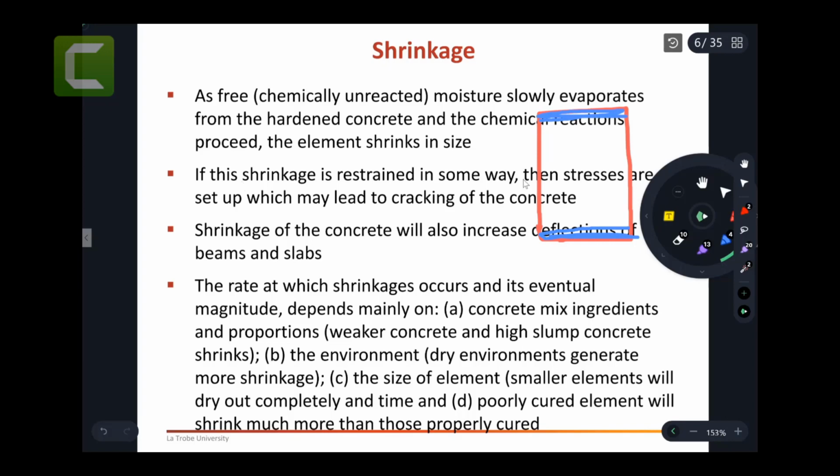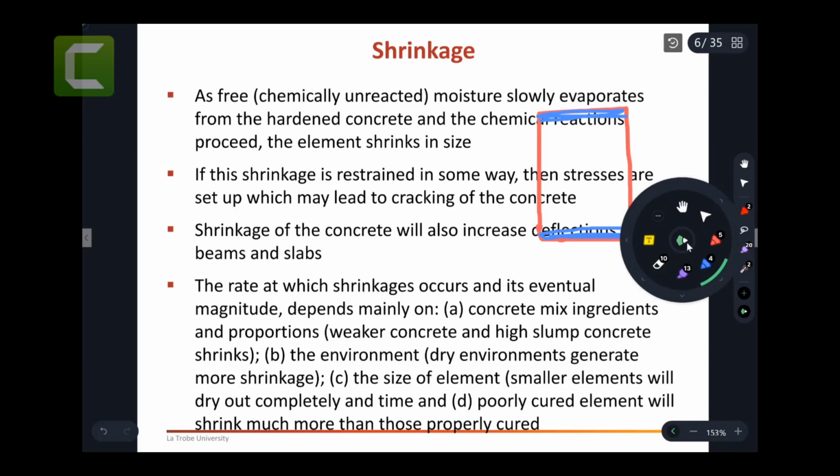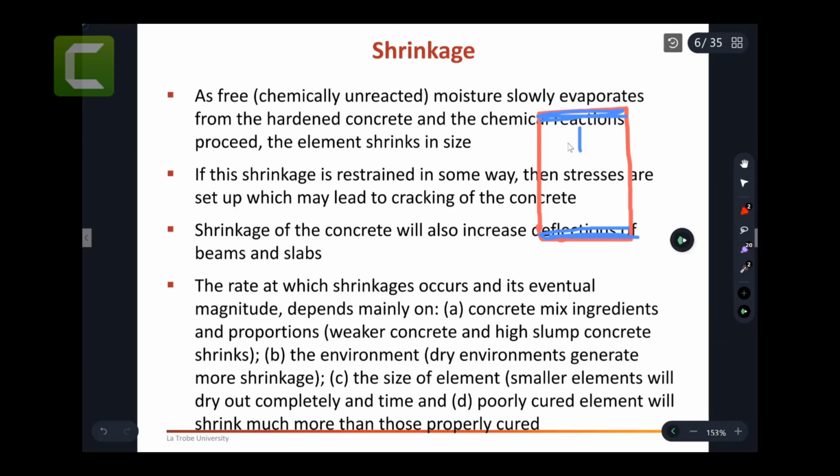Now, statement number 2 is telling you that usually the slab is going to shrink, whether you like it or not. What does it mean physically? It means that it will get shortened. Remember, we're not talking about many millimeters or even a few millimeters. We're talking about 2 or 3 or half of a millimeter, depending on the design. But if you don't deal with these very few millimeters correctly, they're going to end up causing maybe significant cracks or small ugly cracks.